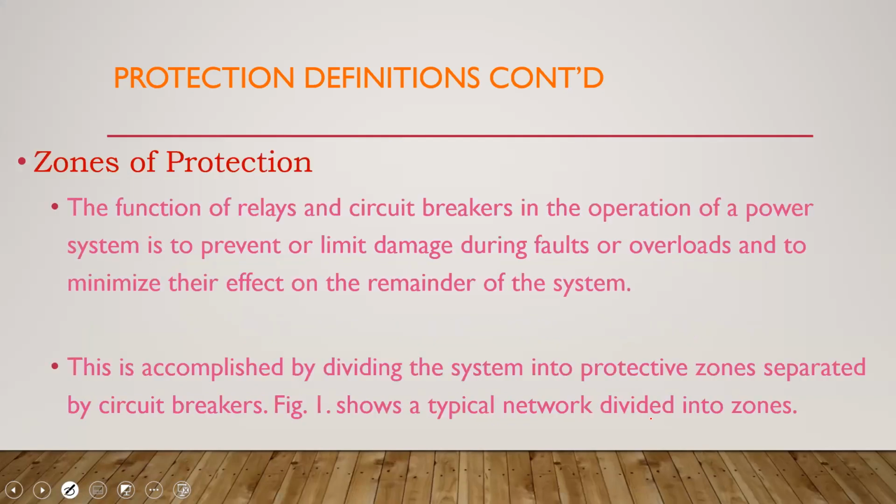Okay, so we now come to what we call zones of protection. This is where I'll try to answer Mr. Clark's question. When we talk about zones, it's really just the equipment and its associated breakers. So when we break up the system into zones, we're really looking at the protected piece of equipment along with its switchgear.